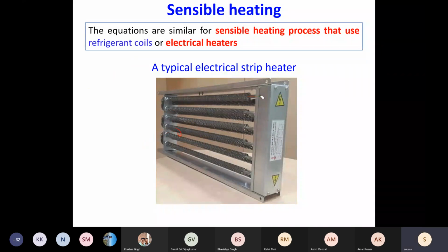Now you should understand the fallacy of the dry mode which is present in your AC remotes. It does not just dehumidify the air, it dehumidifies and cools the air. For it to be just a dehumidifier with no change in temperature, you need an electrical heater again.